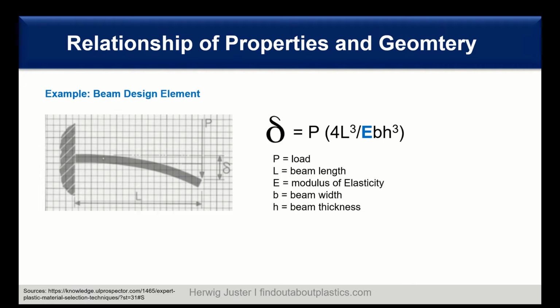So the modulus of elasticity is a material property which can be measured, which is then plugged into this equation. And here in the normal use case, it's always the value at room temperature. However, when your application has a continuous use temperature of 80 degrees C, you have to put in another value to correctly predict the deformation. And this is already one of the key points here,